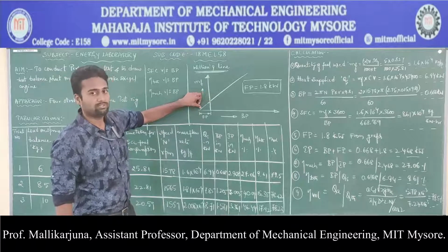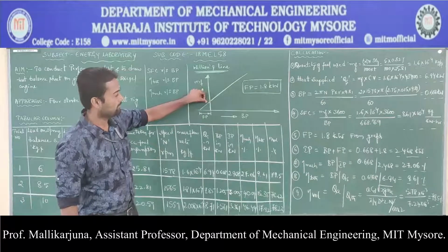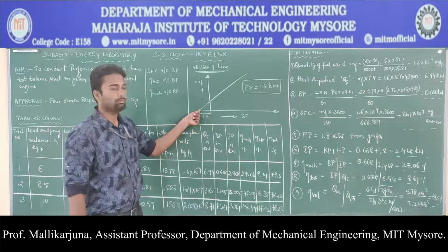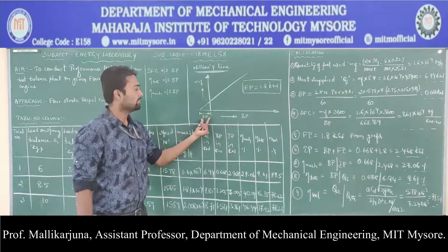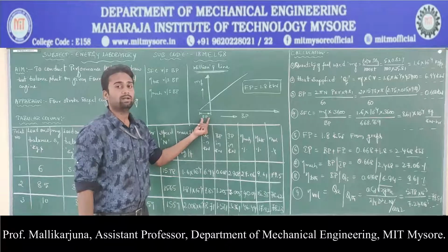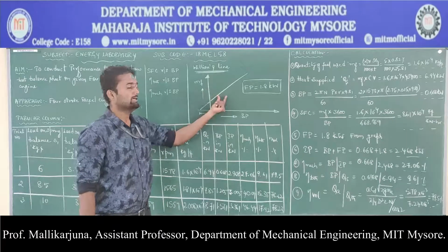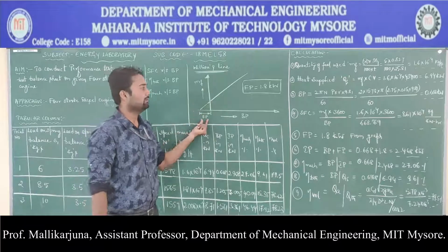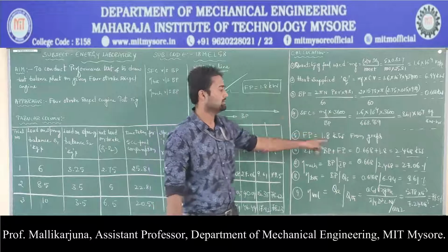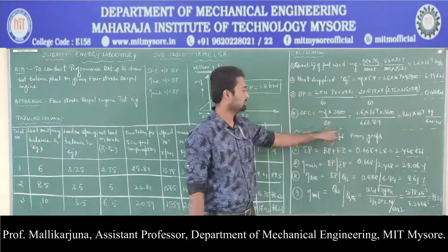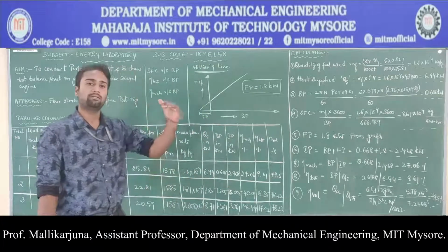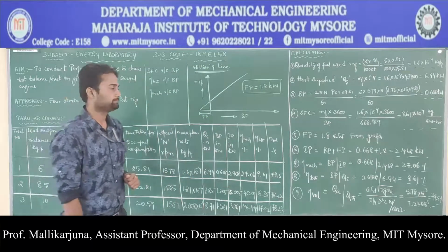It is allowing us to extrapolate the graph backwards. So this extrapolated curve is going to touch the negative x-axis at certain point. From the origin, that particular distance will become the frictional power of the engine. Upon plotting the graph for various trials, this frictional power has been taken as 1.8 kilowatts. That is what we have written over here. So this 1.8 kilowatt is the friction occurred by the engine at that particular speed.